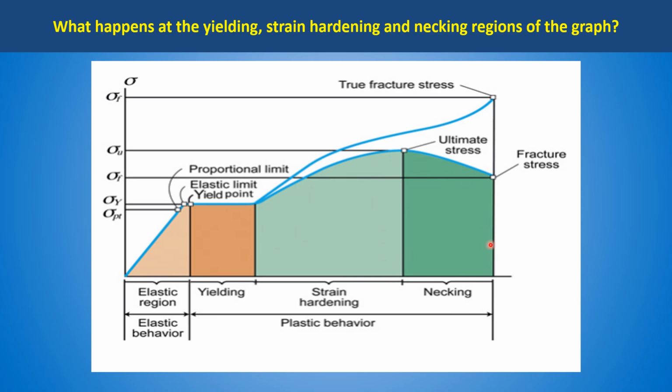And we have here what is known as necking. So after the ultimate stress point, stretching occurs with an actual reduction in the stress. Why? Because we have necking or waisting in the material, where the cross-sectional area is reduced, and it will reduce until we have a gross failure in the material.